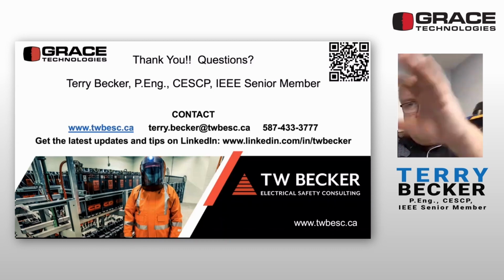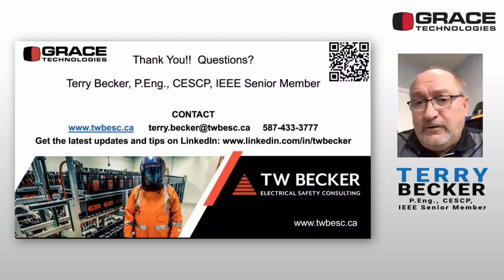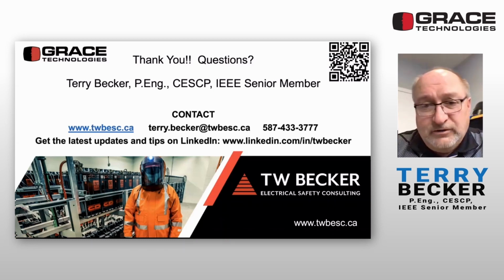So it's a risk assessment that you need to do as the employer. I've seen this video. I've heard this. Some person posted this person was burned from an arc flash, but for how many pieces of energized electrical equipment we have globally and abnormal arc faults and arc flash occurring, it's negligible. But you as the employer analyze your equipment for the likelihood of an abnormal arc fault depending on the work task initiated and arc blast pressure. I said for 65K or less, if you look at the information that's available on blast pressure, it's going to be hundreds of pounds per square foot, not thousands of pounds per square foot that have been previously communicated.